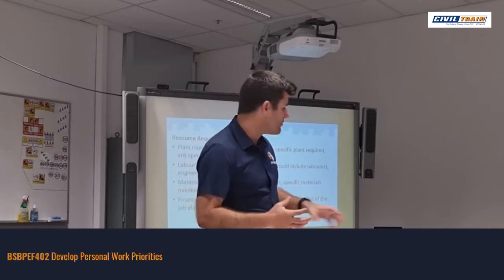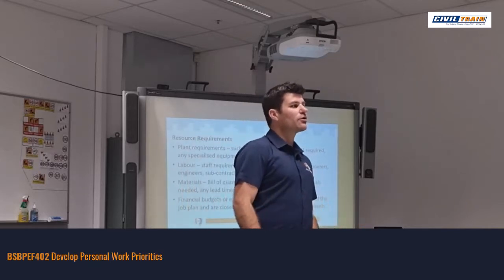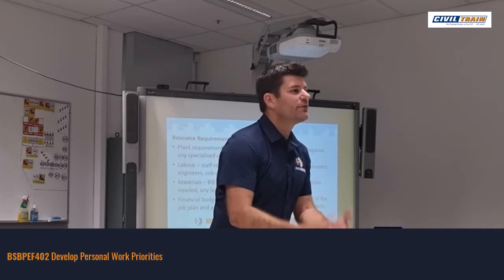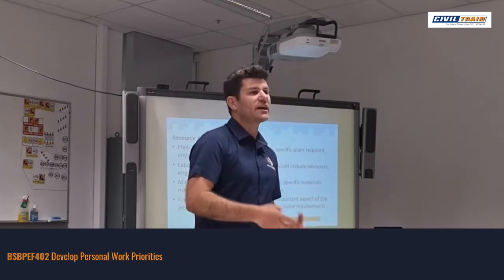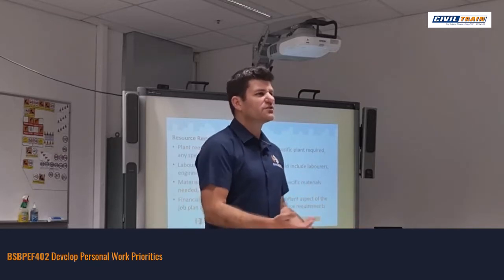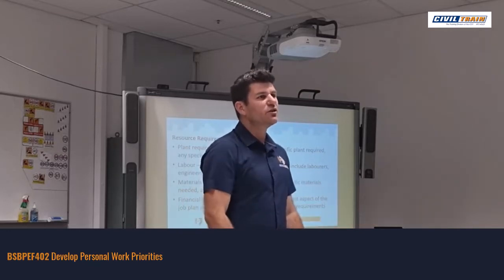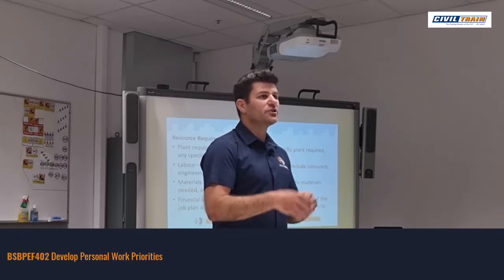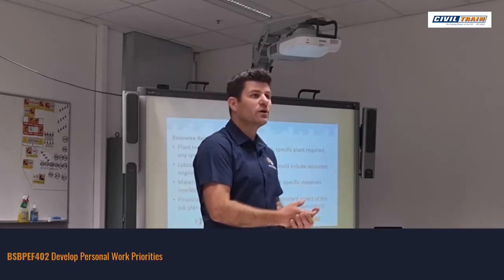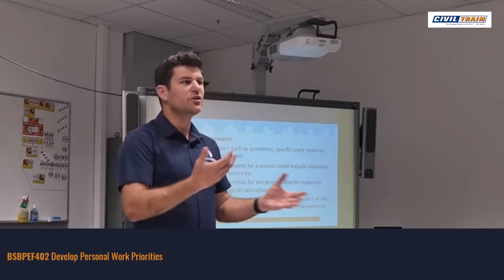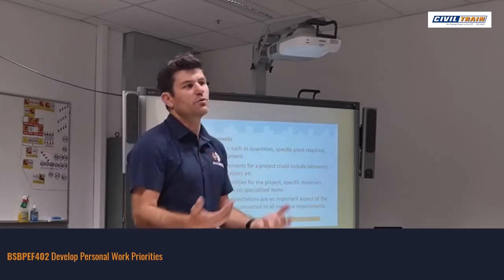One thing I'm looking for realistically though, is when we're planning it, if you've got your concrete pour happening on day 5, and on your key resource delivery, you've got your concrete coming on day 6, obviously I'd see a discrepancy in your plan. So all you're really showing me is you understand the process of planning that, if we're going to do site setup, you would expect to see your fencing and resources arrive on the day or the day before, not 2 or 3 days later. So it's just you guys showing me you understand when you would want those resources.